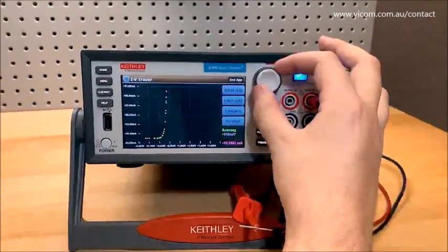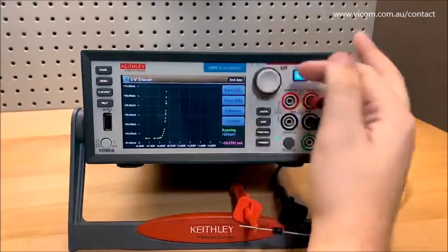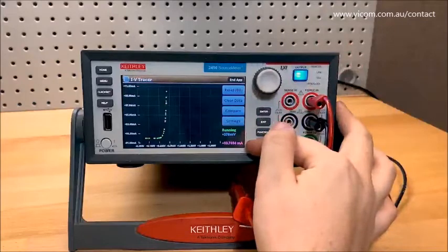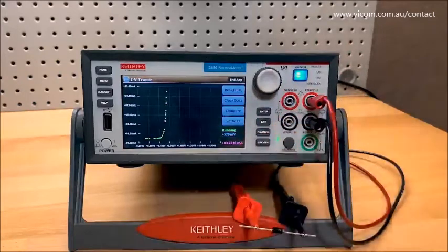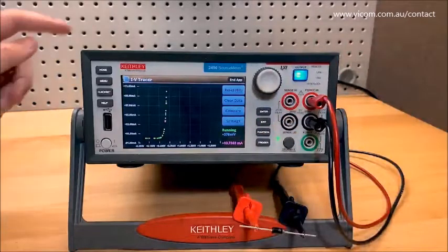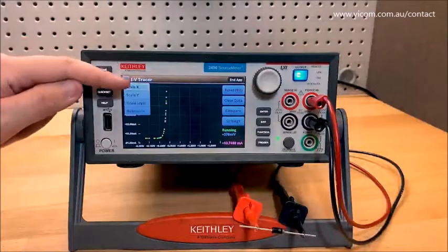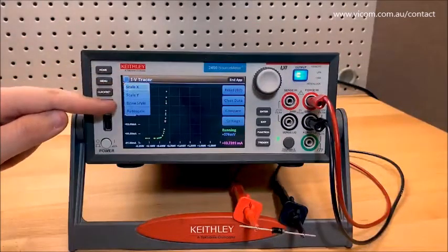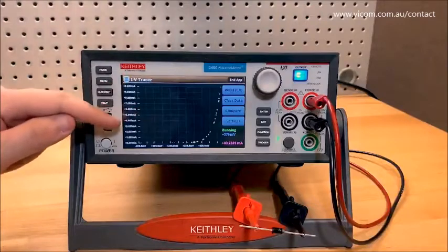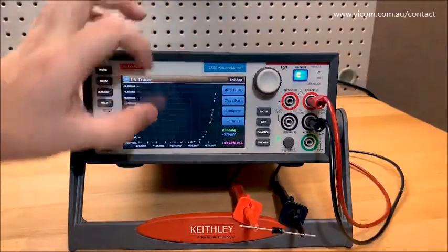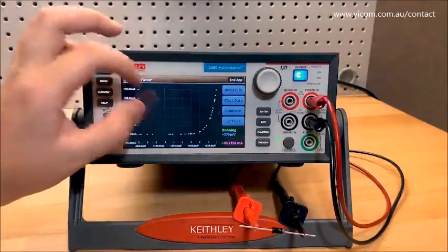If I hold at a single point, you can see the exact measured value continue to update in the lower right, since the output stays on after all. I set my upper voltage bound a little too high for this curve. You can tell because of all the extra space on the right. I'll use the auto scale function to make my curve fill the entire screen. Then I'll adjust the zoom by pinching slightly too.